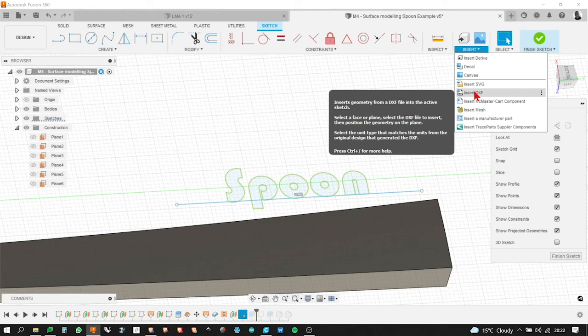There is a really nice function if you ever get into CNC machining with text in Fusion, using a V cutter to get really nice crisp text. It's a longer thing to show you, but there is a really nice technique within Fusion for creating really finely machined text using a V cutter from this kind of setup with text in the first place. Doing an extrude cut, and then the V cutter will create that nicely V'd out, engraved text. So it's being engraved like with a chisel. Yes, exactly. And then it does it all for you, and it's wonderful.